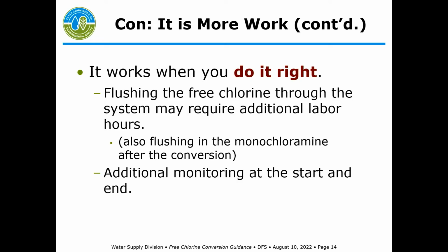and doing all that coordination with your suppliers. They have to go out and check that the valves are working. Another issue is during the actual flushing, when you're moving free chlorine through your system, there's a lot more work for the operators than they normally have. A lot more monitoring, both during the start and at the end. So keep that in mind. To do it right, it is going to take more time, and you'll have to have overtime budgeted, you may have to do that.